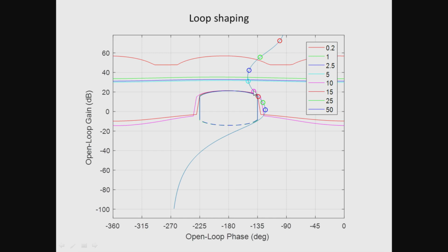Likewise, you can also notice that the loop gain at other frequencies are well above the bounds at those specific frequencies, and the loop shape just touches this closed curve which represents the stability bounds at 25 and 50 radians per second, which implies that the stability specifications are just met as a consequence of this particular controller structure.